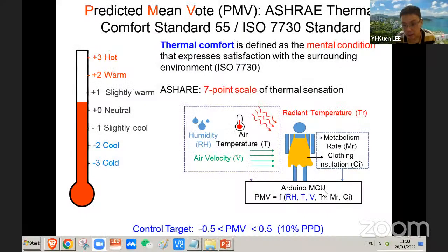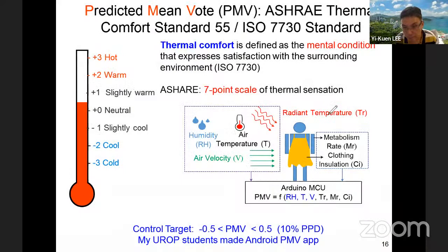Do you understand? So definitely PMV, as I showed you, is one type of human thermal model, right? With about 1,000 people, and this V is air velocity, right? So in this case, if you look at the website I showed you, if you go beyond about 1 meter per second, then they cannot give you this kind of data. So this means PMV does have certain limitation.